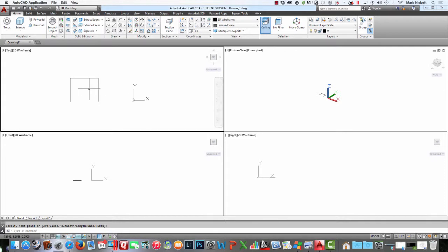The reason I stopped it is because I just want to offset this 1/2 inch, because that's what it is. So we'll use the offset command of 0.5. So we'll offset that down like that. We'll finish this up by connecting up these lines like this.